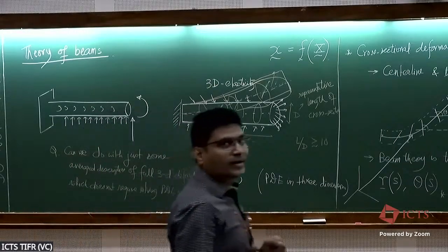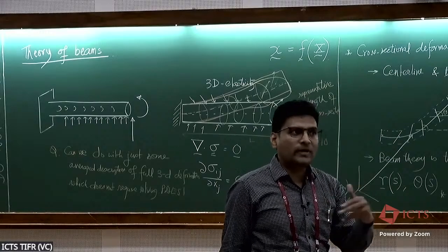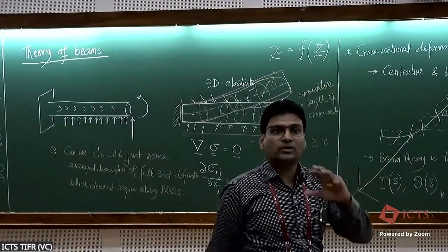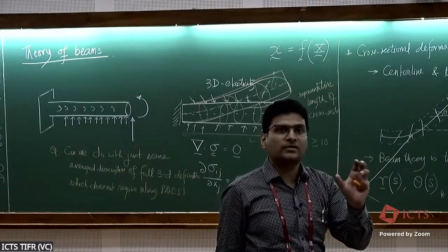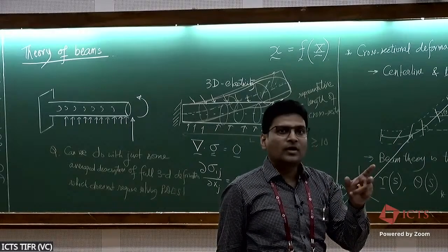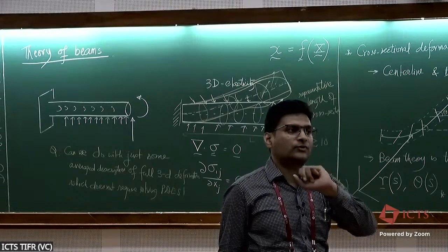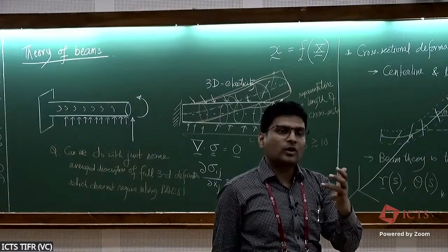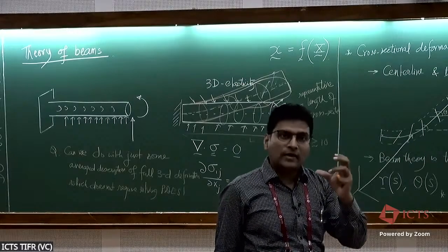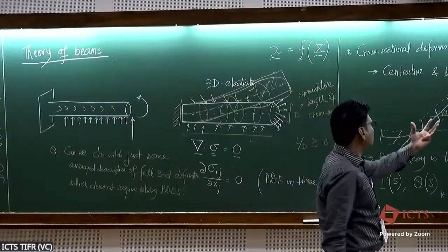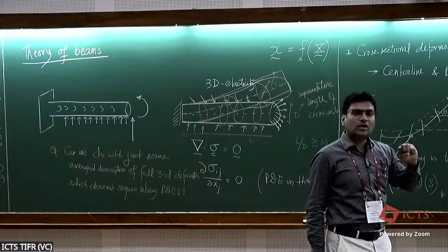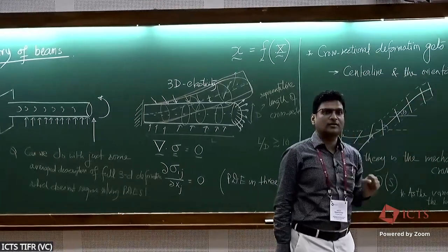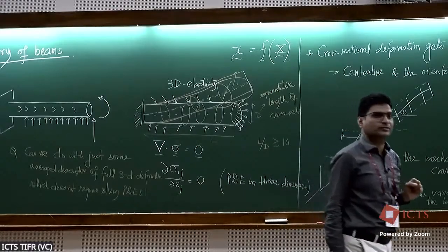It's both. And there is a rigorous mathematical theory where mechanicians prove the center line principle. They have not proved it for the general case, but for special cases they have proved it. When you asked whether it is just with respect to displacement or also with respect to stresses: depending on what you want, if you want stresses to also be within an error, then you have to go more away from the boundary. If you are just happy with the displacement, then you don't have to go so far away from the boundary. But that's a very good question.